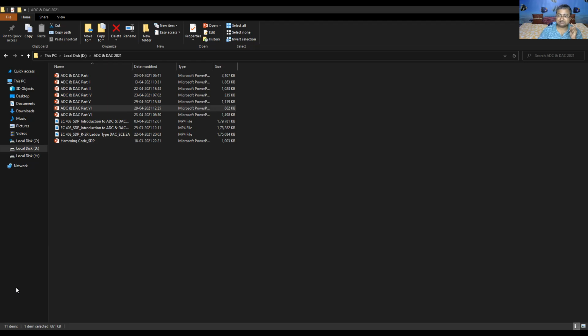Now VC depends upon the output of the integrator. If V1 is greater than 0, then VC will be 0. If V1 is positive, then due to the inverting comparator, the output VC will be 0.